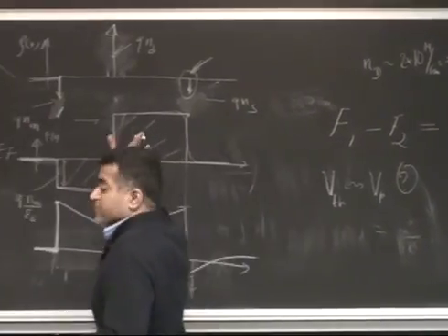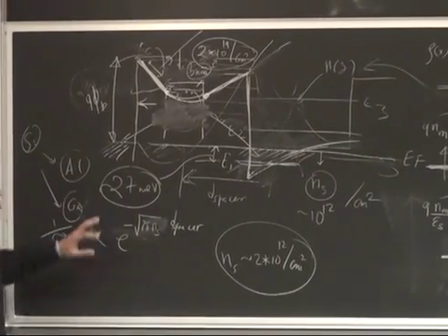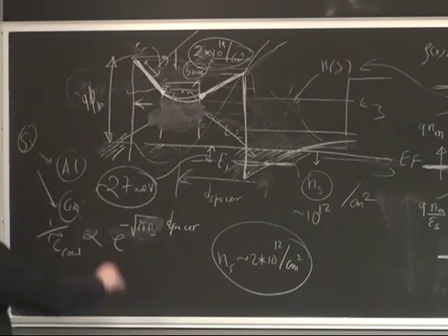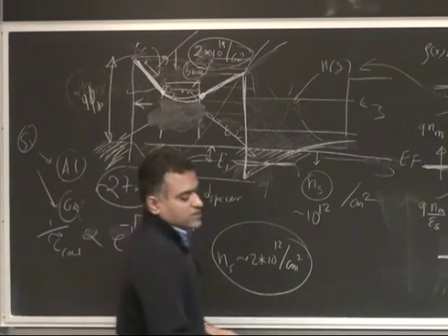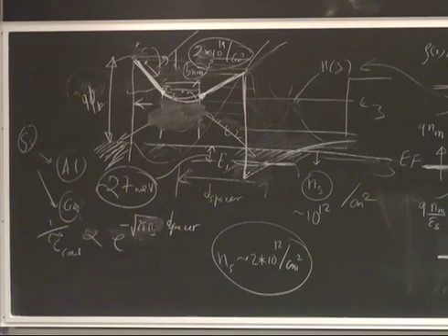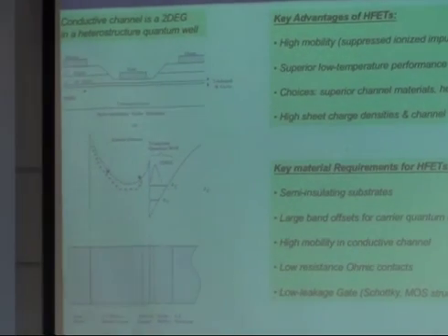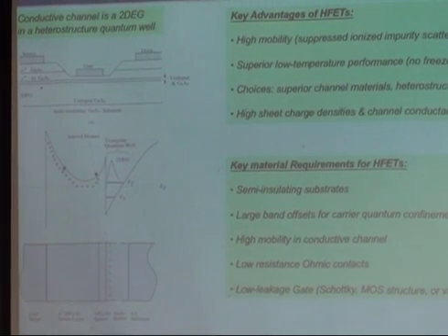And you can say this from the band diagram directly, I mean, this charge field picture, in a very simple way. So you see, at least intuitively, that when I have this metal here and I have formed an ohmic contact to this electron gas, the structure looks exactly like this. So here's the gate, you have a barrier, electron gas here, and I formed an ohmic contact. Do not worry about exactly all the details of this. I think we had discussed slightly last class that essentially you are connected to this electron gas without any voltage drops from the source and drain, negligible voltage drops.